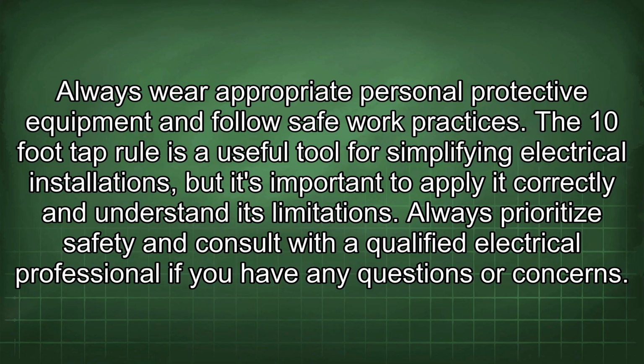The 10-foot tap rule is a useful tool for simplifying electrical installations, but it's important to apply it correctly and understand its limitations. Always prioritize safety and consult with a qualified electrical professional if you have any questions or concerns.